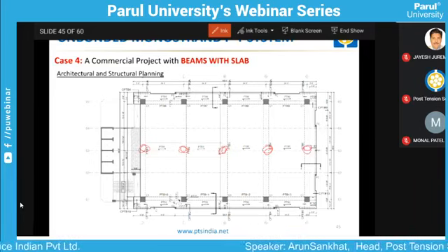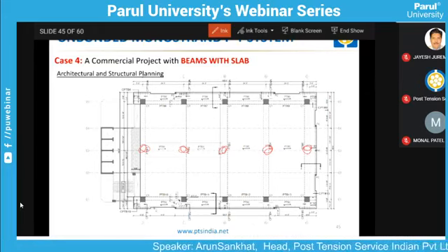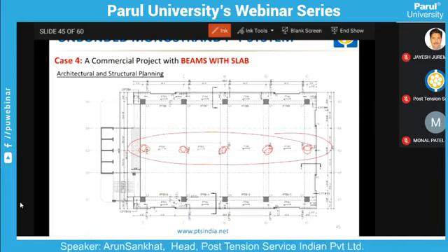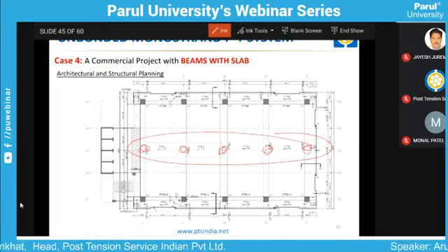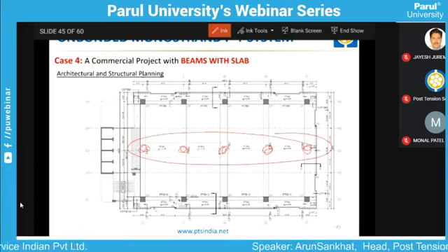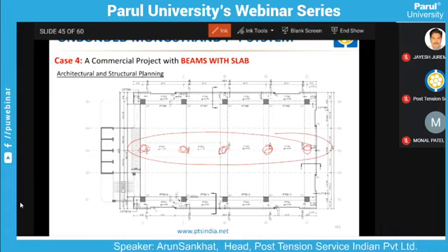With this column, whatever the beam depth and beam width was there, we tried to check without this column, and without increasing the depth of the beam, just increasing the width a little bit, we were able to achieve the desirable design. That is how we opted for this by removing this column, and the client was more than happy getting uninterrupted space in the entire floor.